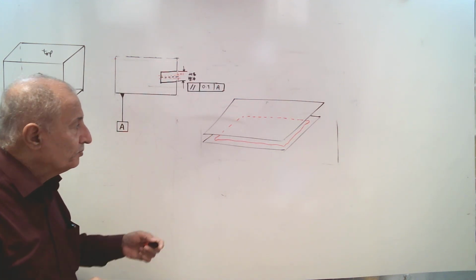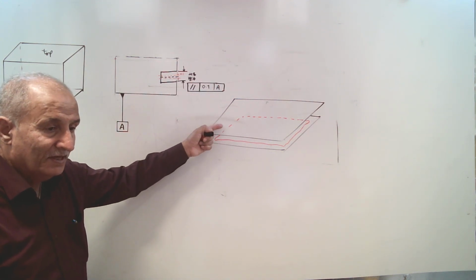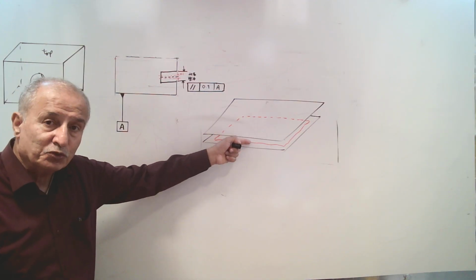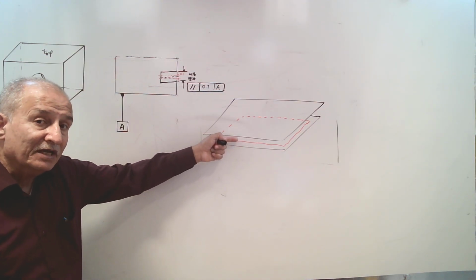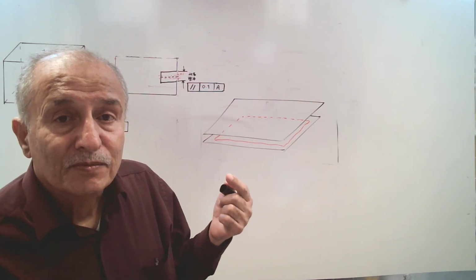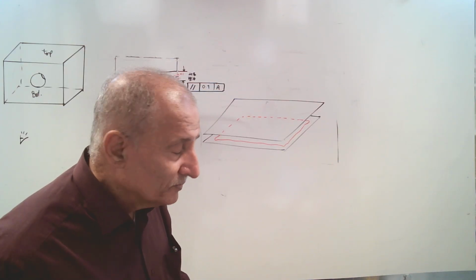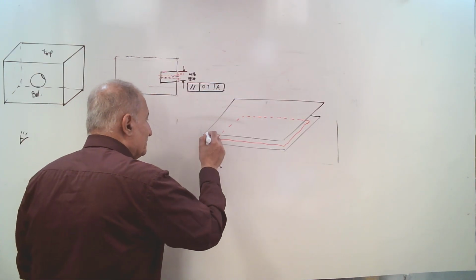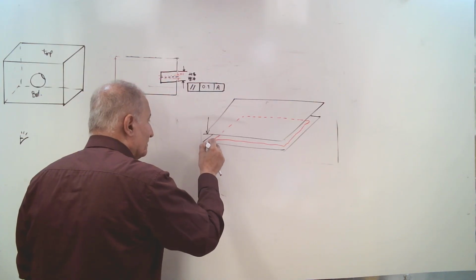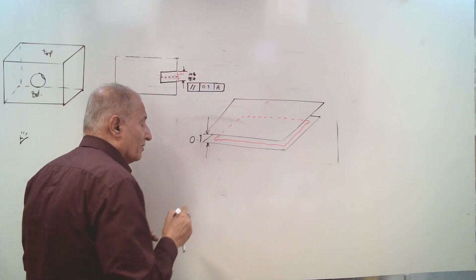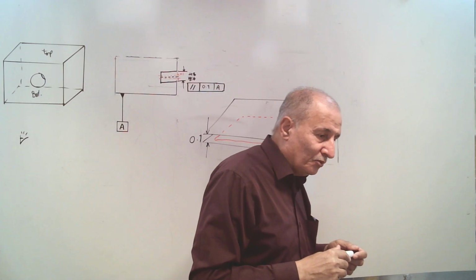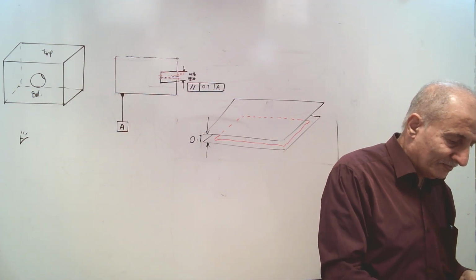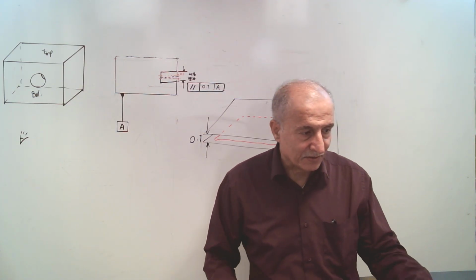Lies between these two parallel surfaces. And this space between these two parallel surfaces is the zone space for this tolerance. And their distance here is 0.1 mm. Zone size.